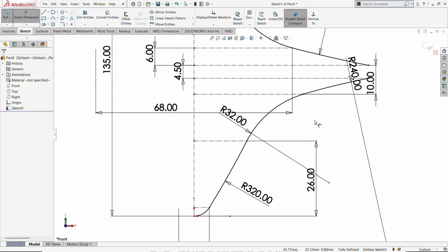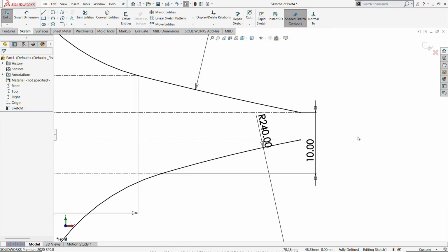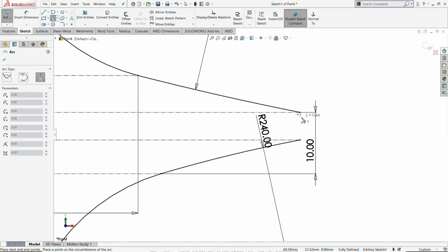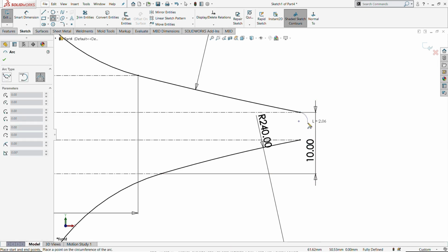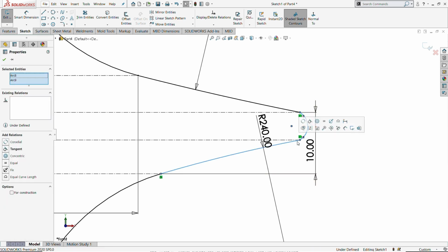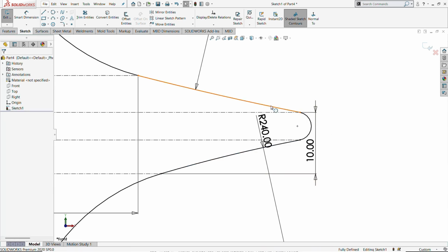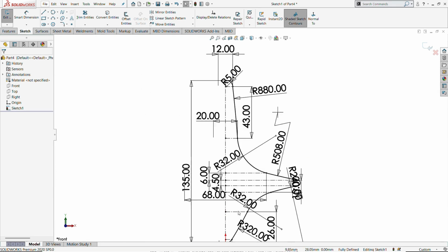Once we mention this vertical dimension, now we are going to close this overall open-ended profile, because it is separated from each other. Just draw one 3-point arc profile at this particular end. Now by connecting the two endpoints, it automatically takes its own position. Now I delete this profile, use a 3-point arc, start from its point up to its endpoint to make a tangential constraint from the bottom end profiles. Now the profiles are tangentially connected with the top end as well as the bottom end.